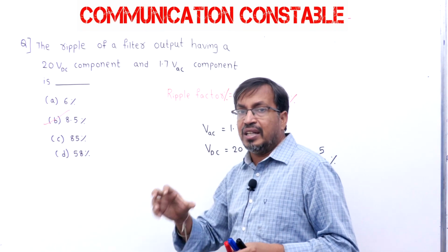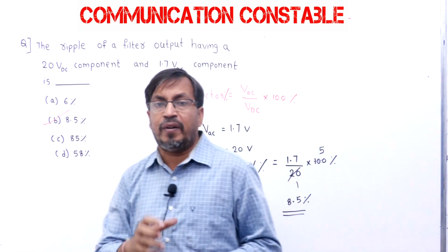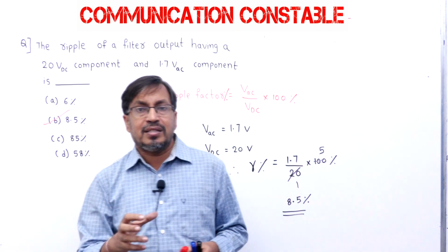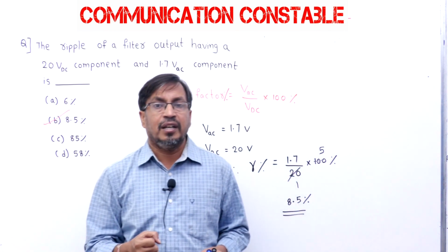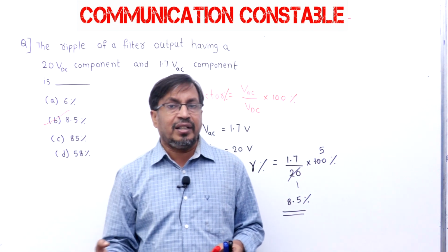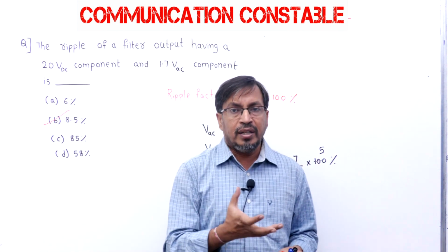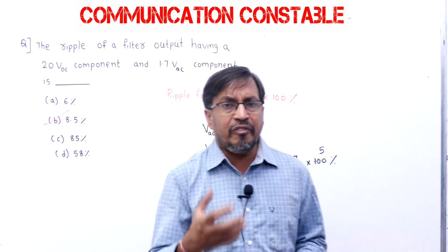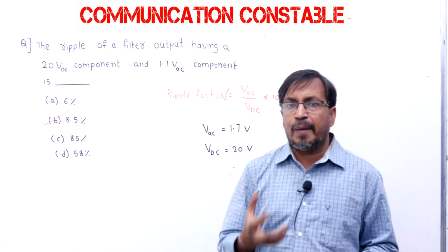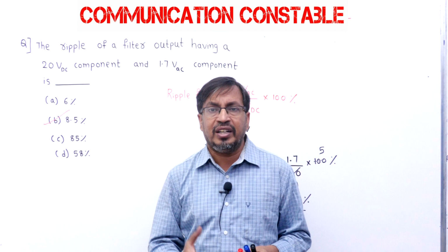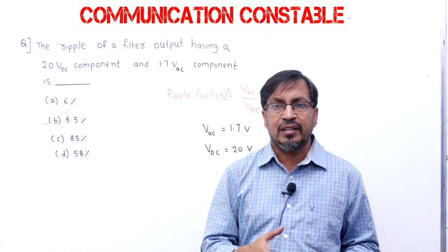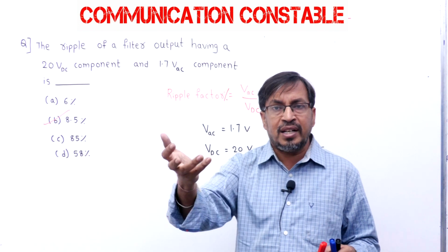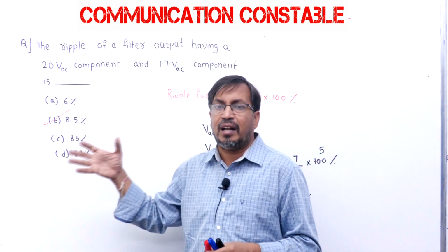Here this filter is used in a regulated power supply to block an AC signal and to allow DC signals, because we are converting an AC input into DC. There are so many filters: inductor filter, capacitor filter, L section filter, pi section filter. All these filters we are discussing in detail in further questions, in classrooms and online.